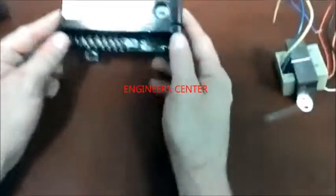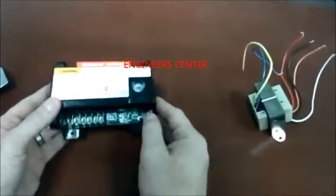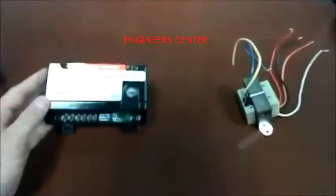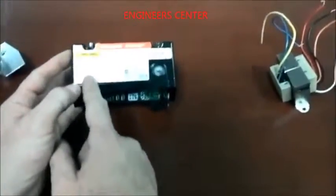And moving on, we have an ignition module, or circuit boards would be the same thing, but these are just a series of relays. It's just on the board, a whole bunch of them. And so if you were to, for instance, give this thing power, 24 volts, you're essentially giving this thing power, and so it's going to respond to your 24 volts. You have to know its sequence of operation now, because I would know that it would start sparking, and then it would energize the pilot valve. You just have to know how something's going to work.